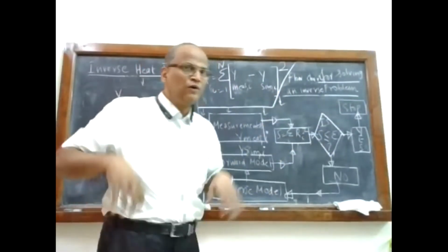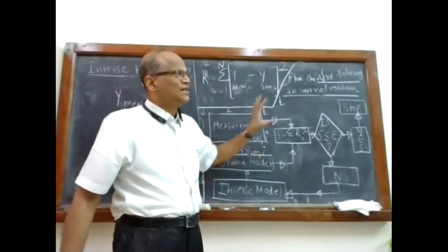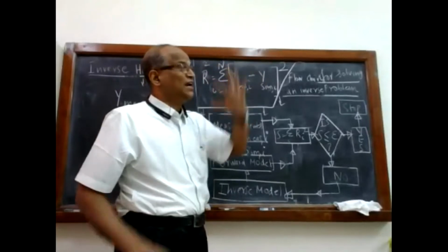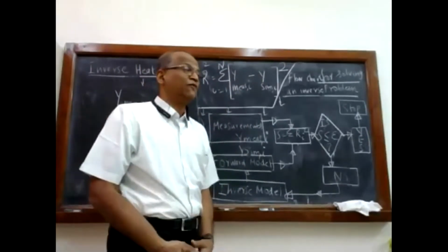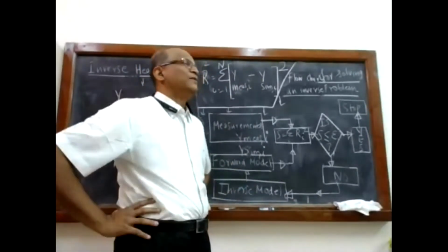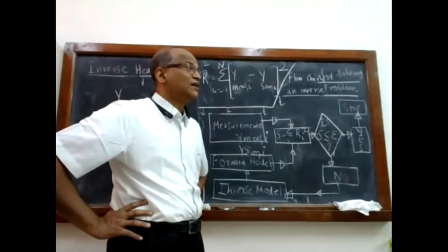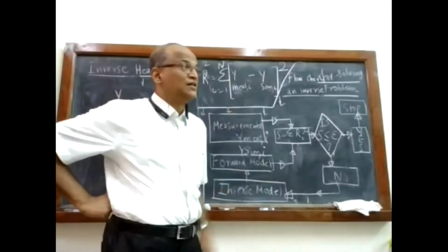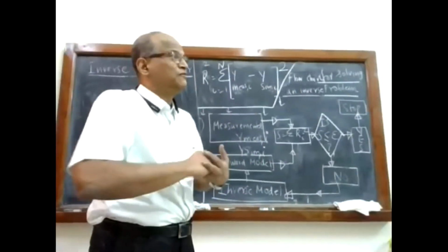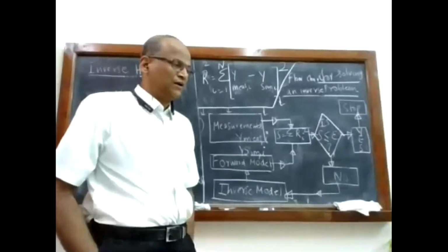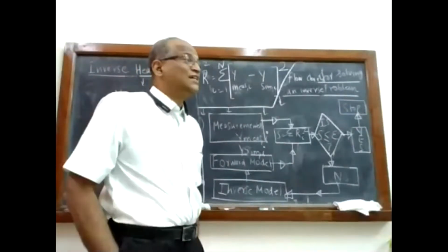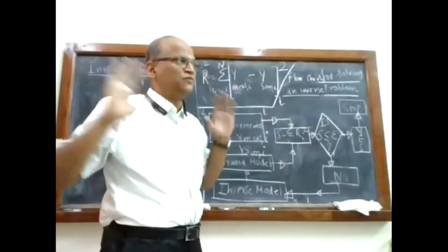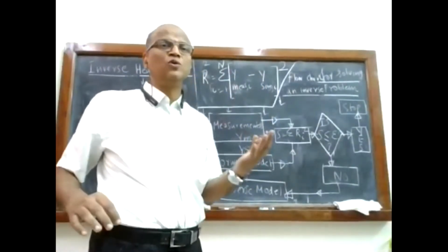Okay. Now, how do we approach? What is this subject? There is a slab. It is giving some measurement. Okay, so it comes in heat transfer. Whether it is coming in conduction, convection, or radiation. Okay, it is coming in conduction. Is it steady or unsteady? Looks like it is steady. Is it one-dimensional, two-dimensional, three-dimensional? Yes, it's one-dimensional. Is it a cylinder, slab, or a sphere? Plain wall. Is there a heat generation? No, there is no heat generation. Okay, now can I write down the governing equation for this? Yes. Now you're cooking with fire.